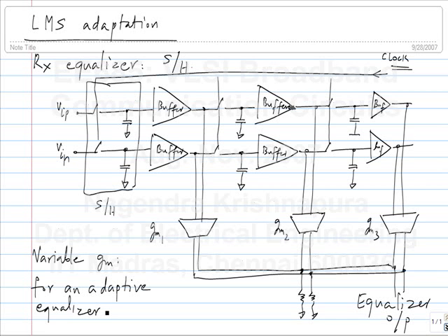What happens if the buffer gain is not exactly 1? I mean, how would you make a buffer? What are the different ways in which you can make a buffer? Source follower. So, some amplifier whose gain is nominally 1, that's usually what you end up using for a buffer. The input impedance should be high, that's the criterion, right? Now, if you make an NMOS source follower, you know the gain is not going to be 1. Even a PMOS source follower, the gain will be different from 1. So, what happens? Will the circuit work even in that case?